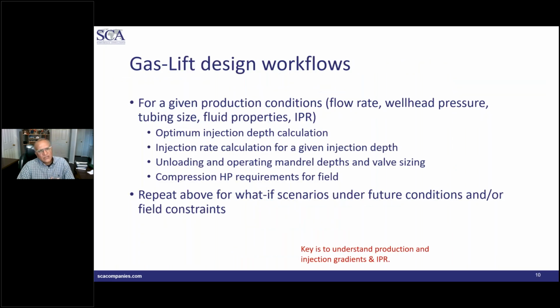Okay. Typical design workflow, as I mentioned earlier, you're trying to determine what is the depth of injection, and what is the injection rate for a particular given injection depth. And then initially your wellbore may be full of completion fluid. And so you have to remove that completion fluid before the regular injection or the gas lift normal process can happen. So you have to figure out the location of these unloading valves. Also, you have to figure out what is the compression horsepower requirement for the field.